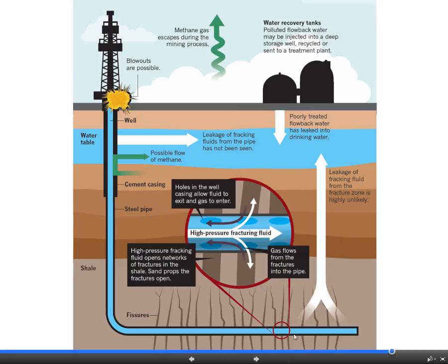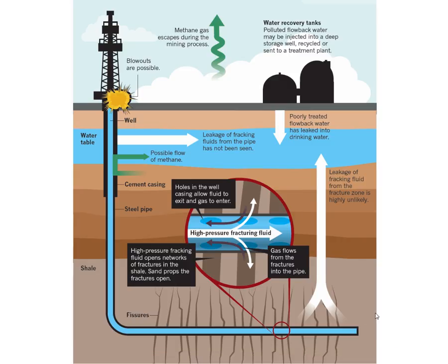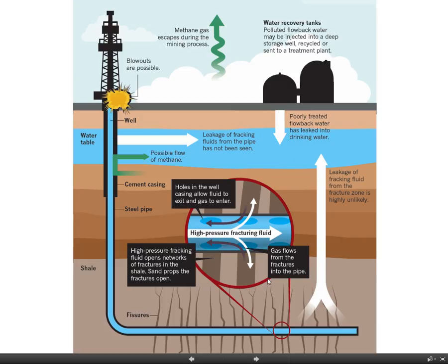So they come back further along, back towards the heel, and detonate maybe another charge over here, and then when that's exhausted they come further back and detonate. And so they work their way back, detonating charges, releasing the natural gas that's trapped in the rock, and that gets pushed back up with the fracking fluid. And eventually when they're done, they'll seal up the pipe with cement, basically to make sure that if there is any residual stuff left, it's not going to leak out and you're not just going to have gas slowly pouring out the top. And that's basically how it's done.